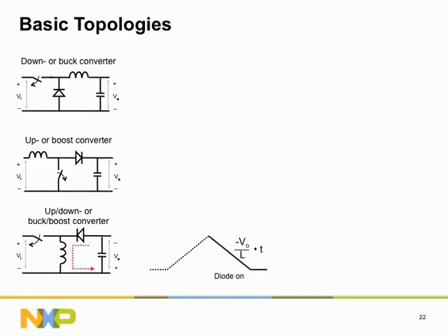In the secondary stroke, the current in the inductor keeps flowing, but it can only take the path indicated by the red arrow. Through the diode, the current charges the capacitor. Also during the secondary stroke, the voltage across the inductor is constant, namely minus Vo, which causes the current to decrease linearly with time. This is shown in the waveform graph on the right-hand side.